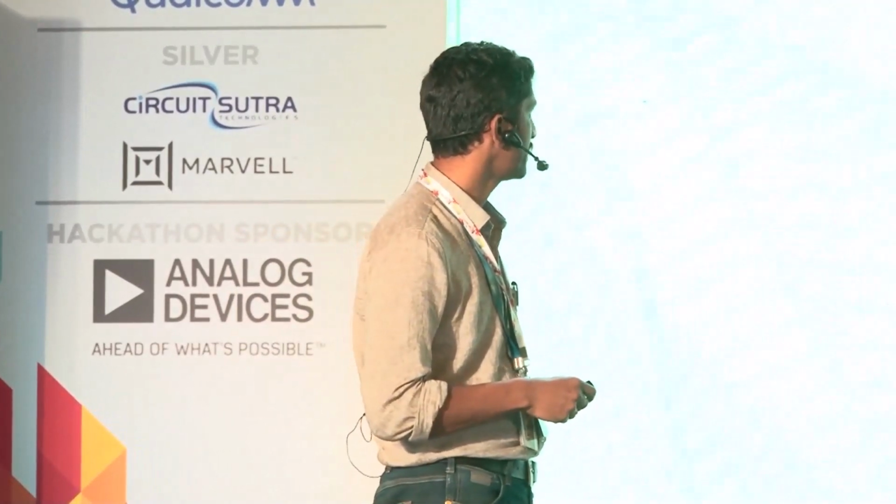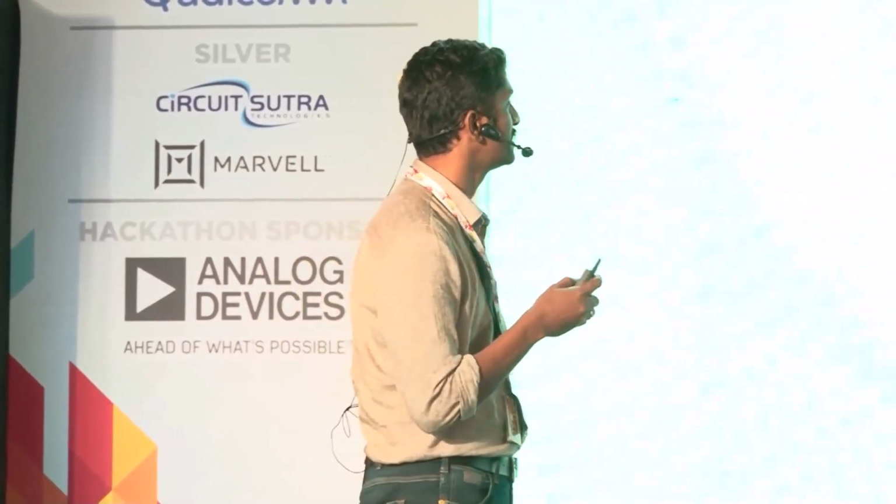So what is the tool flow methodology of this? Basically, my design needs to be synthesizable. That is the first prerequisite. Through our lint and CDC, we make sure our design is synthesizable. Once the synthesizable design is fed, the design is analyzed, and on analyzing the design, the properties are extracted from the design. The tool will generate the properties for you. Then we can prove those properties. It's a brute force kind of thing.